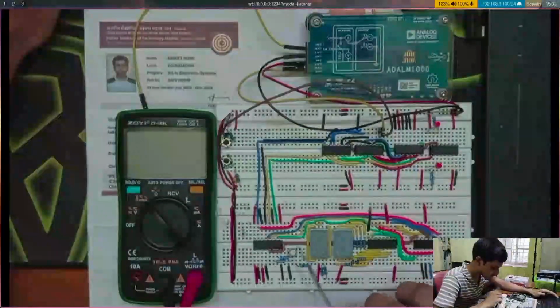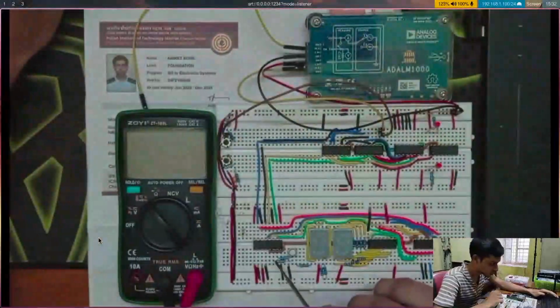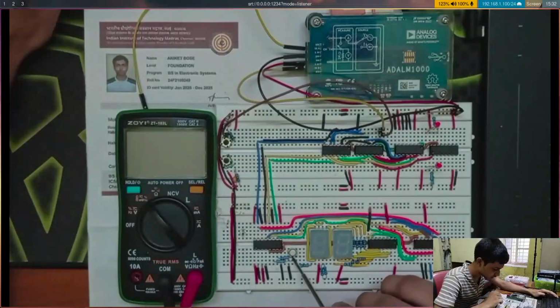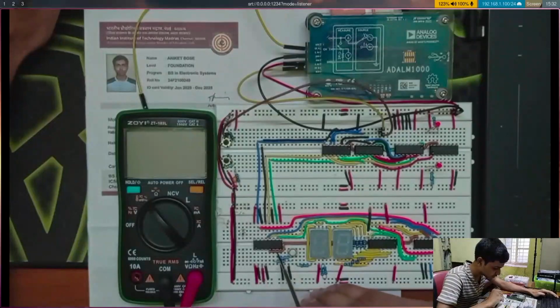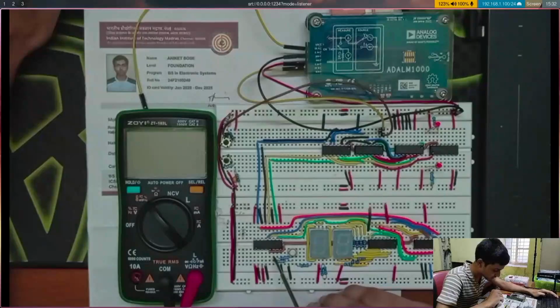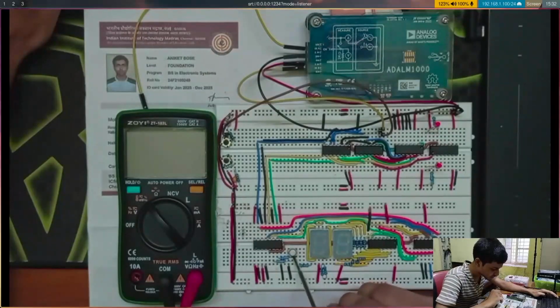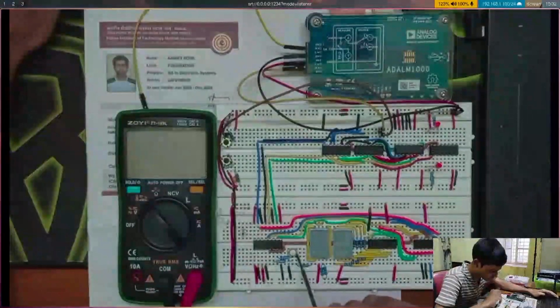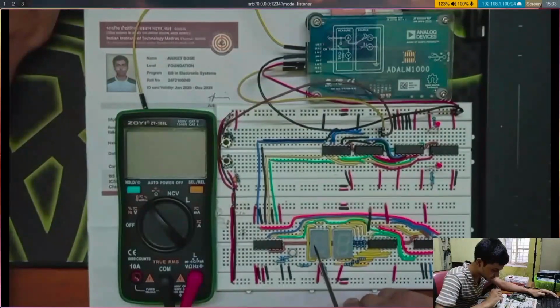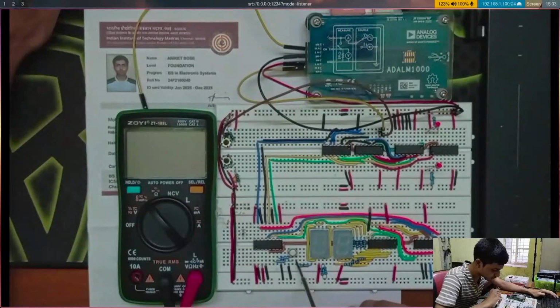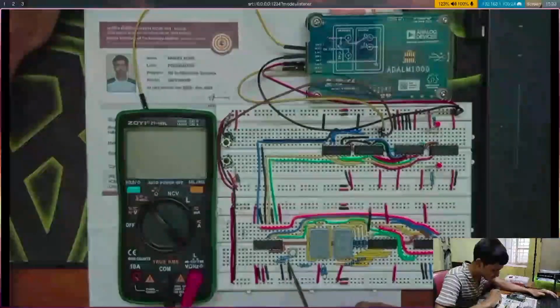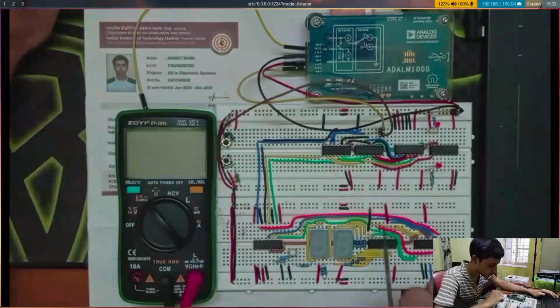For the tens place, I have used this BJT with A greater than. So here you can see there are two resistors. So these two resistors are driving this base. So this resistor is connected to A less than B out, and this is connected to A equal to B out. So whenever the counter output is less than 9 or equal to 9, this base is going to be high, and that will pull this collector low. In effect, this collector, which is connected to these 4 segments, first, second, third and fourth, so these 4 segments will get turned off because the collector is going to be pulled to the ground because this base was pulled high. So this way we are going to show the numbers.